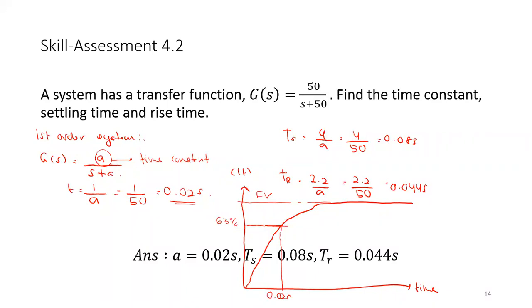So also the rise time is somewhere here at 0.044 seconds. So this is the rise time, and the settling time, the time it takes to settle, is somewhere around here, 0.08 seconds. Ts and Tr.